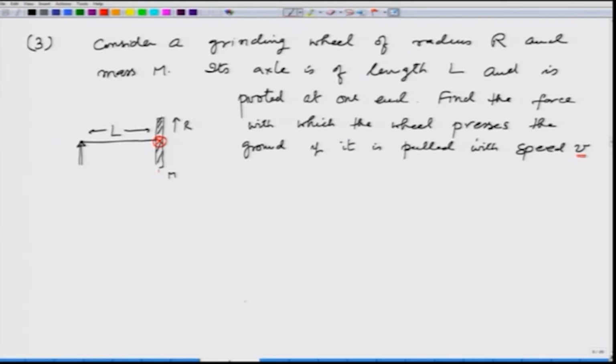And why that happens is because of this. If this is going in, then the way it is rotating, the upper portion is going in, this portion is going into the board, and this is coming out, not the board, the screen, and therefore, it has a horizontal angular momentum LH. As the wheel rotates, LH is going to come out of the page, and therefore, there is a torque required which is coming out of the page.